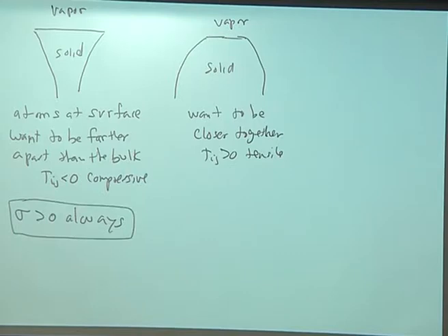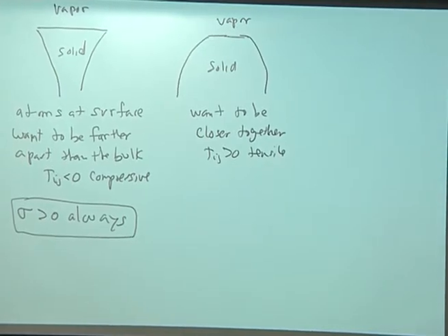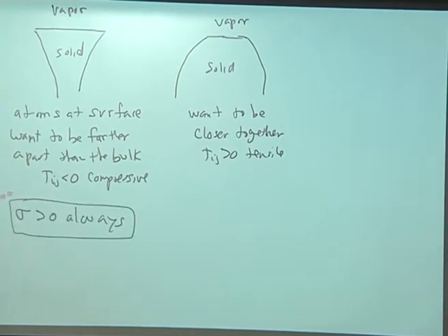So it's like going into your Cahn-Hilliard equations and changing the sign of the gradient energy coefficient to be negative. It's just like doing your spinodal decomposition with no gradient energy coefficient and having a negative diffusion coefficient. Things just kind of blow up, right? Same idea. The interfacial energy has to be positive, but the stress can be either tensile or compressive.